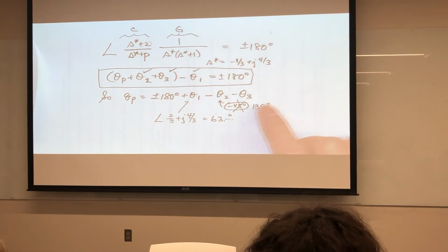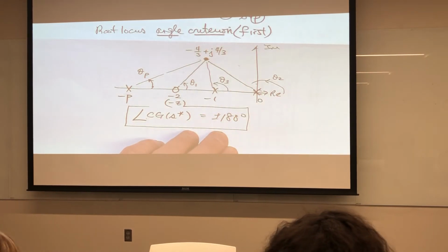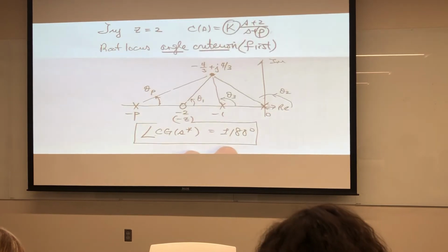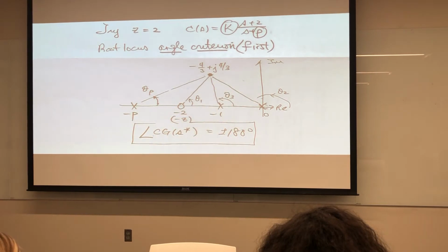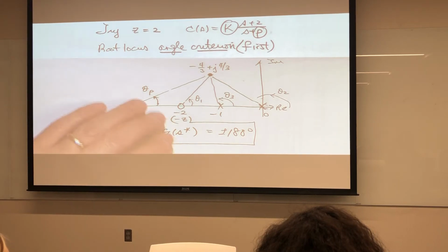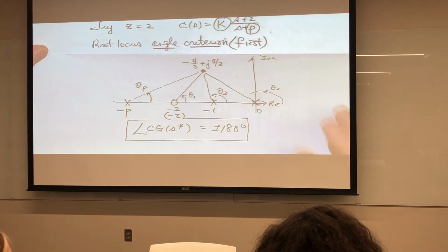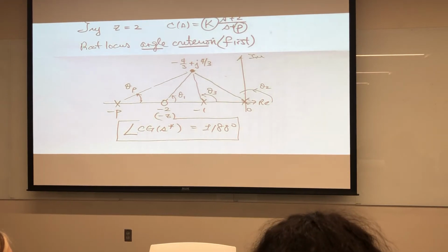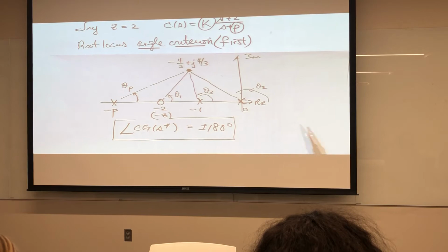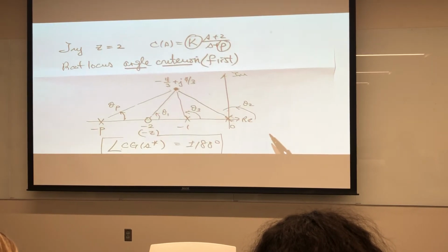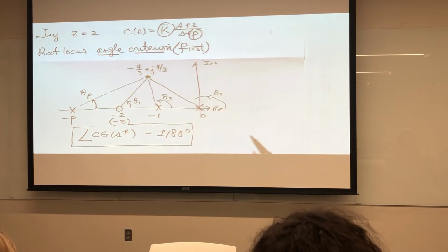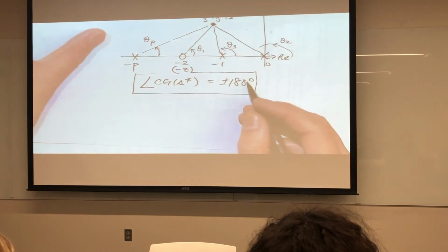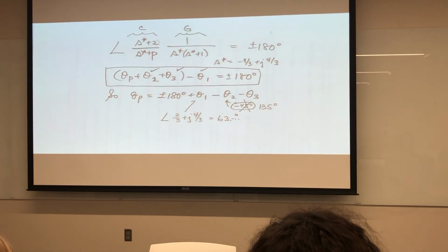You have to ask yourself, does the answer make sense? Now, if you are punching in a complex number, real part and imaginary part, and doing a rectangular to polar conversion, then probably it will not give you a funny answer. It'll probably say it's 135. Since they're related by 180, why does it matter? You could argue that it doesn't matter, but it will, because our solution says that everything has to add up to be plus or minus 180.